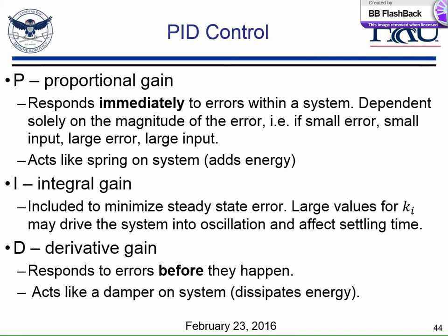And then we can add a D term. So we're actually going to improve the transient response, with less overshoot. Settling time can stay about the same. So with the PID, we can kind of get the best of each one of the controllers, right? But it does come at an expense because it becomes a little bit more difficult to tune, right?